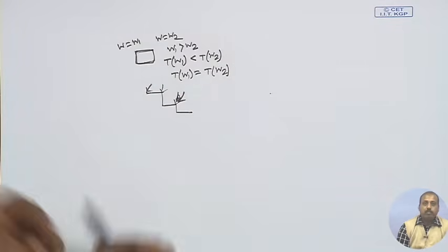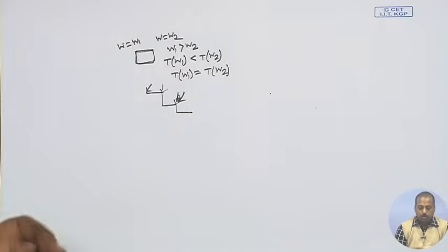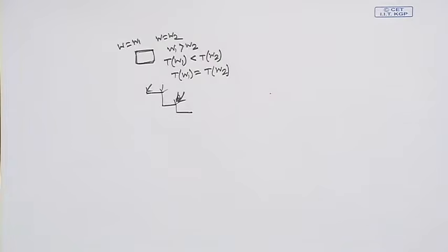This may be due to some functional module inside the core that takes a huge amount of time, maybe some very long scan chain has been kept there. As a result, whatever TAM line we assign to it, the time is going to be dominated by the length of the scan chain, and assigning more TAM bits to the core does not help in improving its test time.